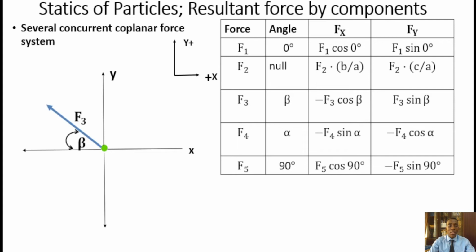Similarly, for F3, draw a rectangle like we have been doing, x component, y component. Now looking at F3 here, the x component is towards this direction, and so it is F3x. And then the y component is in this direction. But look at this. This is positive. However, this is negative. You know, we said every force this way is positive and every force this way is positive. And this is the reason why we are getting this result here.